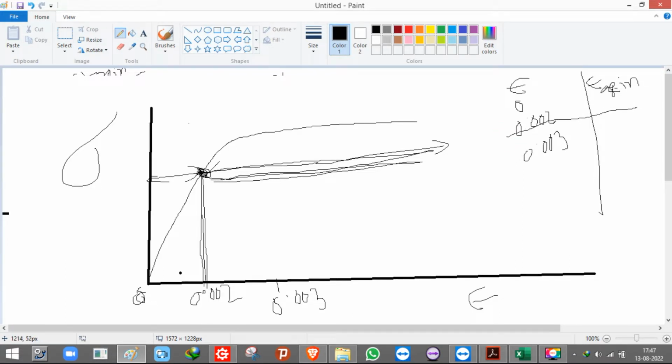So what will be the inelastic strain over here? It is 0. Why? Beyond this point the inelastic behavior starts, and up to this point we have elastic behavior. So at this point, though the strain is 0.002, this strain is elastic strain, and inelastic strain, 0.002 minus this strain, will give you 0 value.